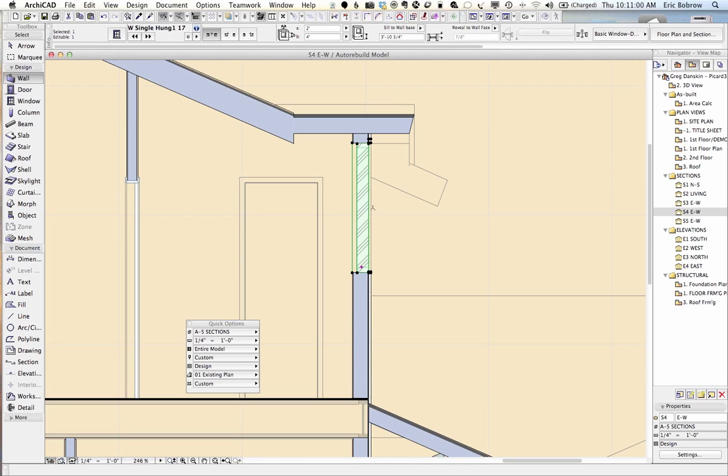Okay. All right. So right now, a few comments there. This particular window is set to have a specific sill height. So in other words, you told it that you cared about its sill height rather than its head height. If I say I want to switch it to looking at the header, then it would be saying 7 foot 10 3/4. So that's what it's set at.